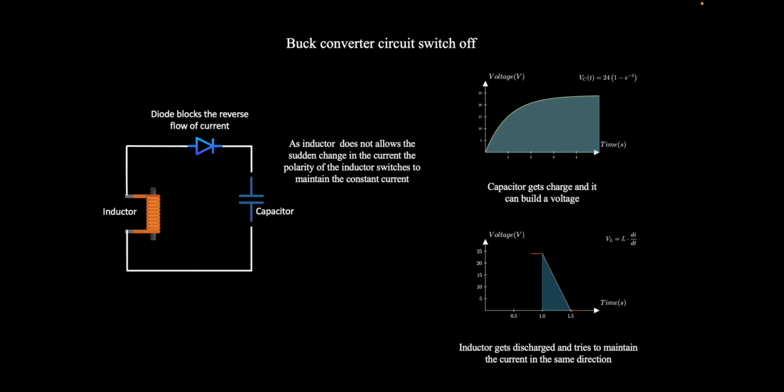But over here, as you can see, the capacitor voltage is gradually rising because there is still current flow happening. But now the inductor voltage is decreasing because of the current that is flowing out of the inductor, because the inductor now is responsible for maintaining the voltage across the capacitor.